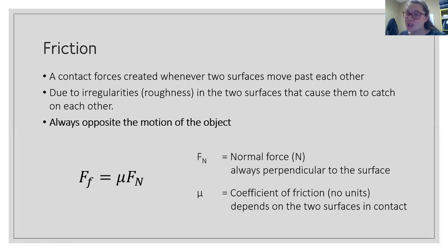That is something that is a concern in most trades, because friction with surface roughness, something rubbing together, results in heat. Whenever we have heat result, that means some of the mechanical energy is actually being converted into heat energy, so we're going to lose efficiency. Not only that, but if the temperatures reach the right temperature, it can cause deformation of metals or materials or structural issues, which results in problems for us and can result in mechanical failure. So friction is something that's important to consider.